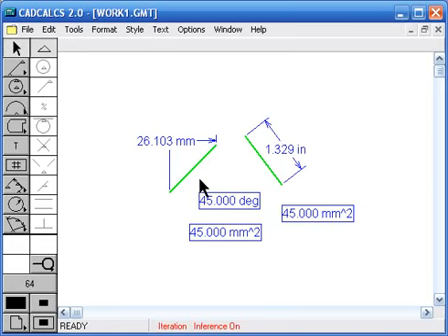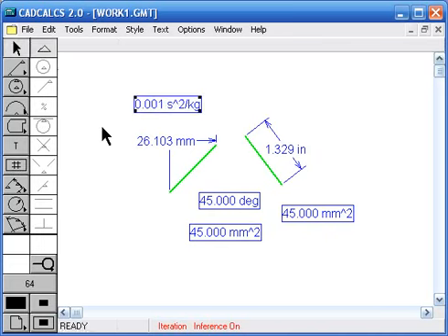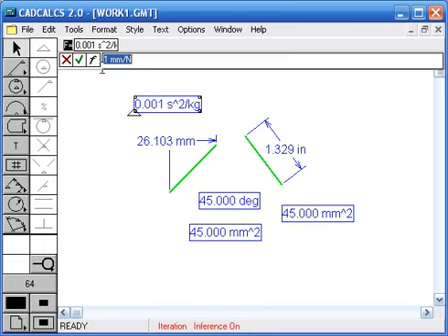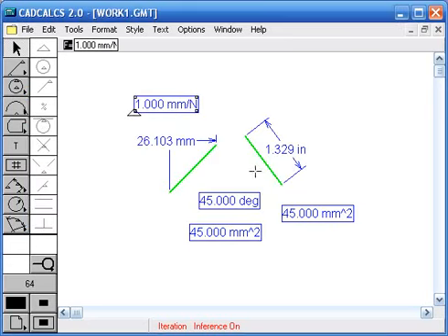And let's say you have a need to use a composite unit. So let's say I'm going to set up a cell here. I want to set up a force scale, so it's 1 millimeter per Newton. Since millimeter per Newton has not been defined in my unit library, in my unit system, it goes and converts the units based on the all units. So I have two choices here. I can click on this and come back here and say units. I want to say millimeter to the power. I enter it manually and it'll give me the unit.